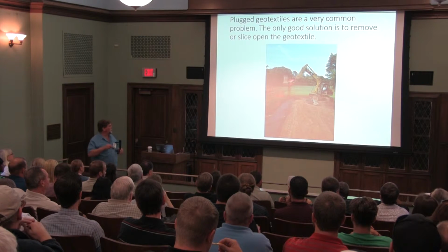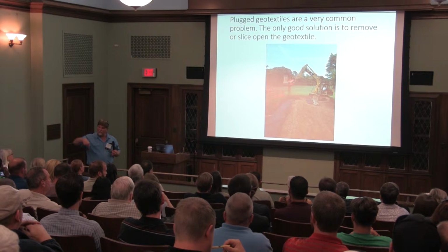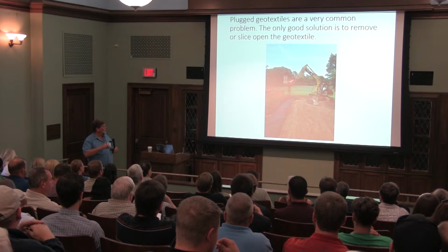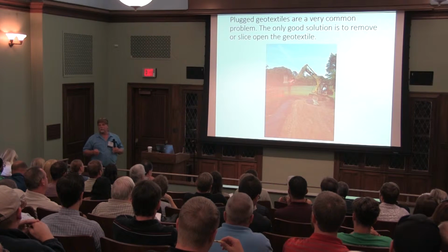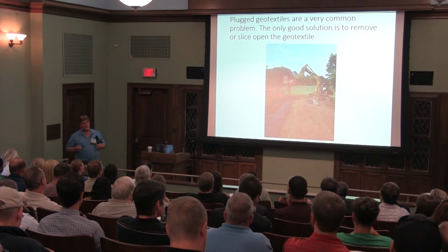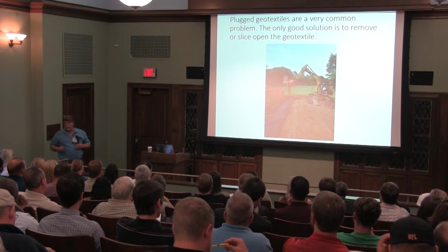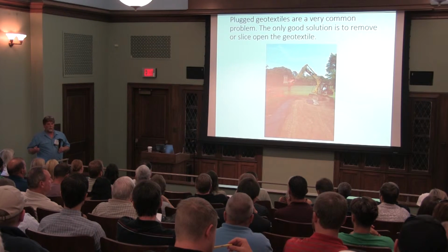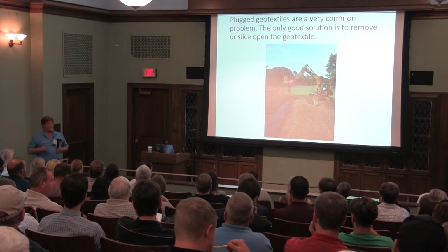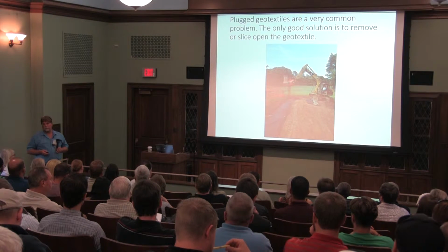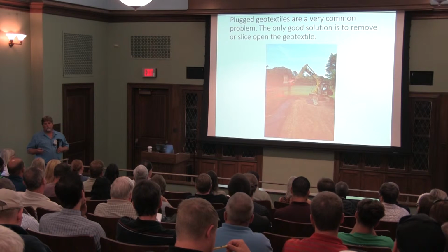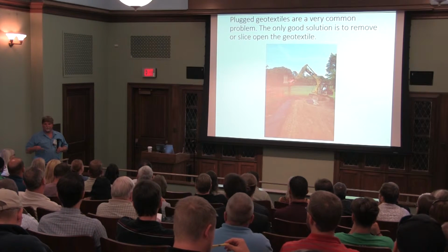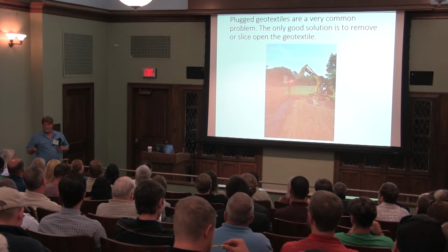If we were trying to infiltrate into that gravel, this Geo Textile has a very, very, very high probability of getting plugged. When you have failures in a rain garden and you have an issue, the very, very first thing I always ask anybody is, did you have Geo Textiles? Were you using Geo Textiles? Most of the time that answer is yes, and we tell them, well, guess what you've got to do now? Cut the stuff full of holes, dig it.